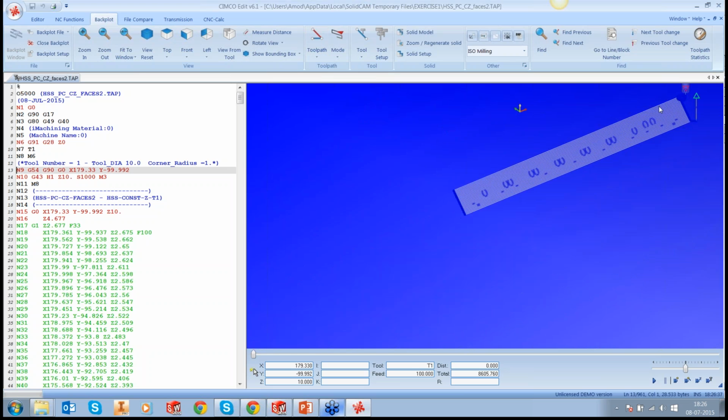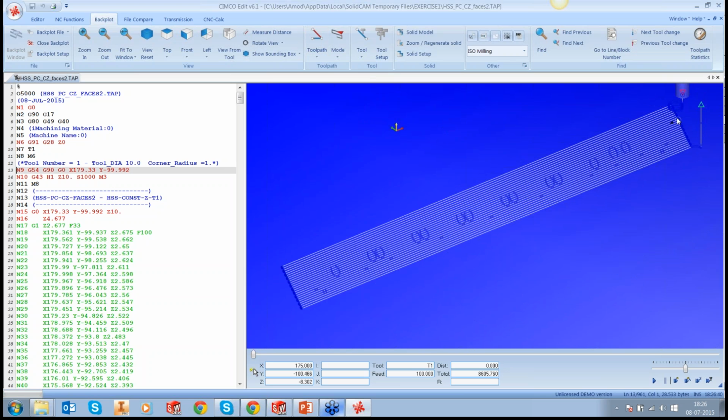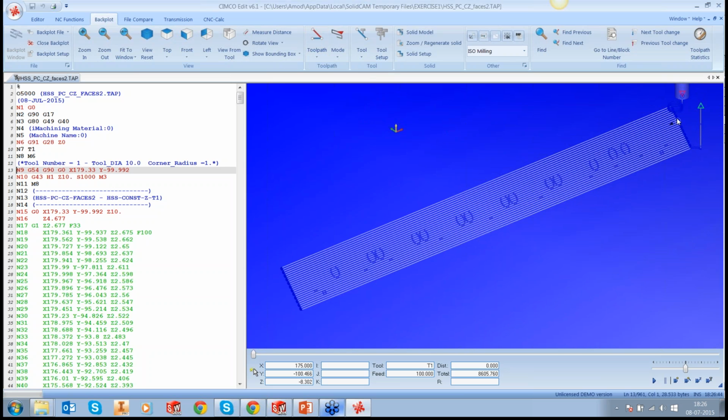Now sometimes if you have a very sophisticated kind of machine which has got its acceleration and deceleration not great, but it's there, and if that is kicking in, you will see that if you're given a feed rate of 1000, it'll take some time before it achieves the 1000 feed rate, and then it goes 1000 and starts decelerating again towards the end. This can cause surface finish issues on your surface.